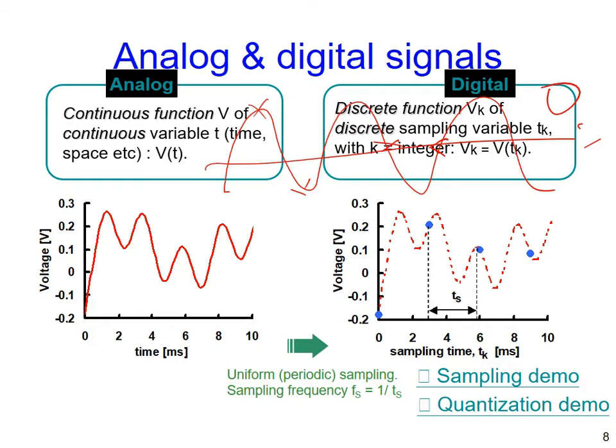Even if you follow the recommendation or Nyquist rate in theory, there is still some chance to make this one wrong. So it is required to be more than, instead of equal to, larger than 2 times your highest frequency.